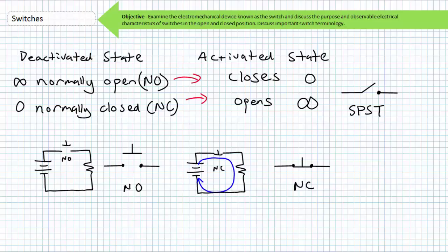The single-pole, single-throw switch I previously used was something known as a single-break switch, and that there is a single point where the single pole breaks or makes contact with its single throw. The normally open and normally closed switch I'm using here are still single-pole, single-throw switches because there is one moving contact and one position it can be placed in.